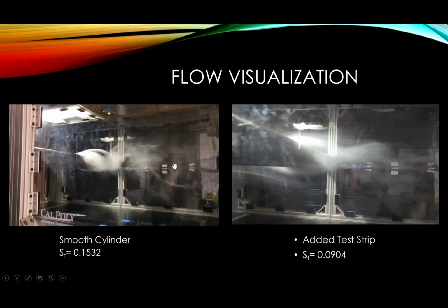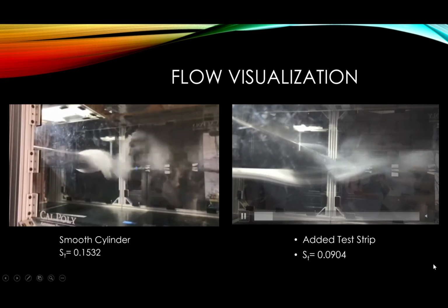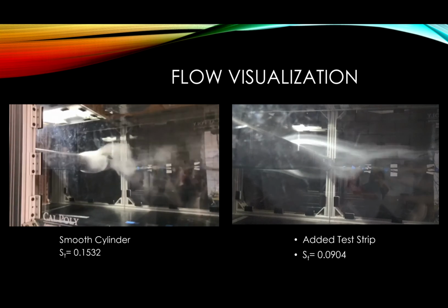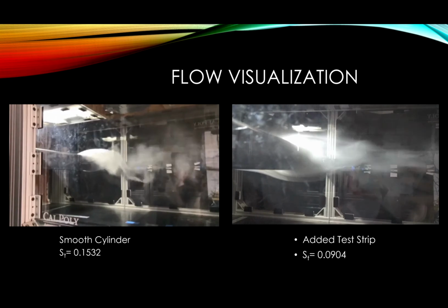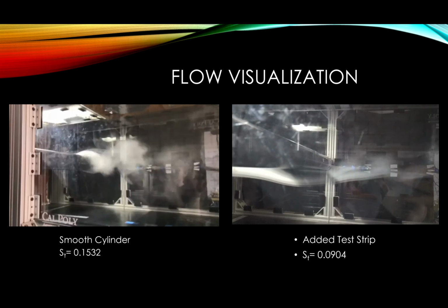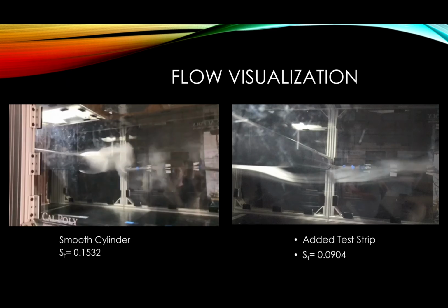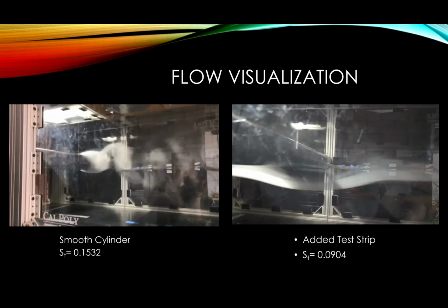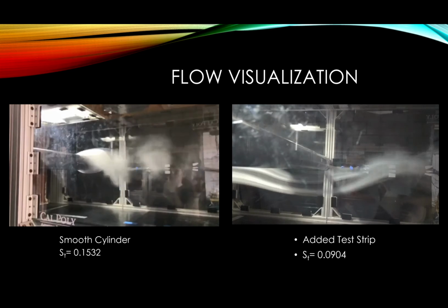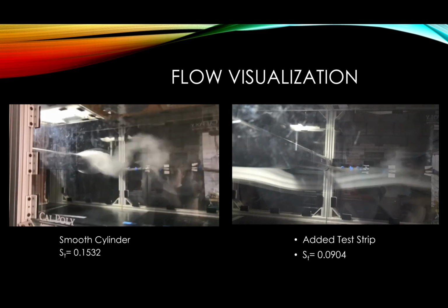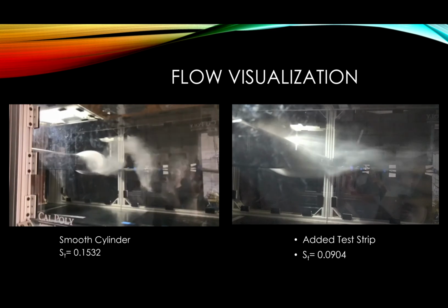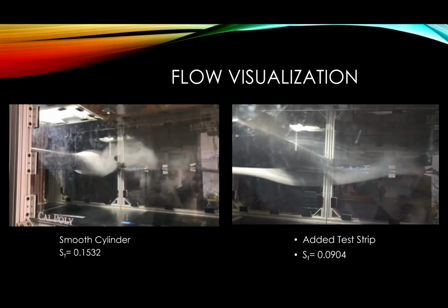This is a side-by-side comparison of the cylinder without the trip strip on the left and with the trip strip on the right. Both are tested at the same Reynolds number. While it looks like the vortex shedding frequency is quicker on the cylinder with the trip strip, it's actually slower. The video on the left was shot by a superior iPhone X at a higher frames per second, so it looks slower, but it's actually not. But if you look closely, you can see that the trip strip decreases the pressure drag exactly as intended, by delaying where the vortices begin and decreasing their size.